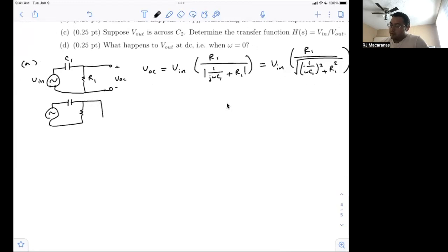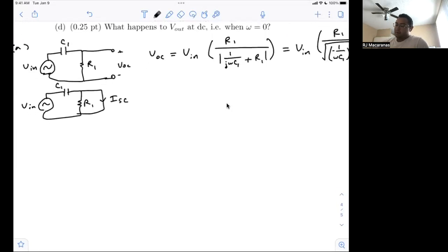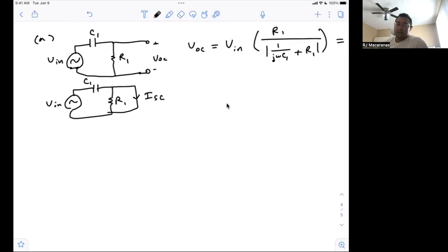Right, and I think a lot of you did this whole process in lecture, so I'm going over how to do it here. R1, C1, Vn. So what happens when we have a short in parallel with the resistor? So that equivalent resistance is 0 times R1 divided by 0 plus R1. So that equivalent resistance ends up going away. Whenever you have a short in parallel with a resistor, the resistor effectively goes away, right? So all the current is going to take that short path.